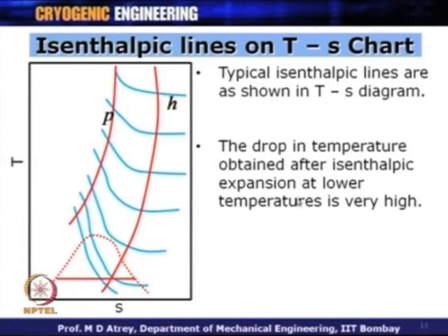So, normally you find that JT expansion would be for a two-phase system when you are completely away from ideal gas. So, you have a mixture of, let us say, gas plus liquid, or complete liquid also, which is normally preferred in order to have more and more cooling effect if the two-phase mixture is subjected to JT expansion. Why is this happening? This is because the gases are imperfect at very low temperature, and therefore, they show the real gas behavior, and they are completely away from the ideal gas nature in these cases.